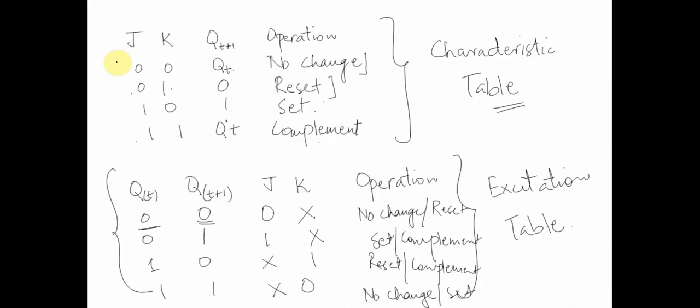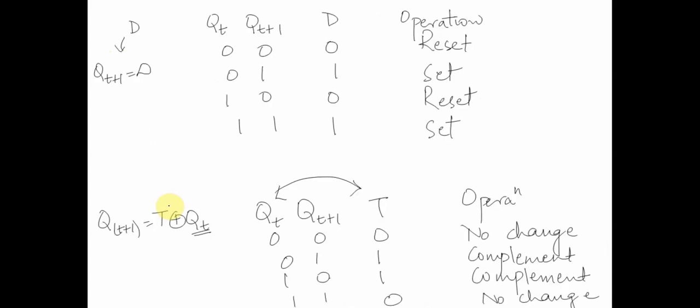One thing I want to quickly capture over here is that we spoke about excitation tables, right? We saw this is the excitation table of the JK flip-flop, and this is the excitation table of D and T. Once we notice, if given a scenario where we have to implement a circuit, it's easiest to do it using a D flip-flop, because in a D flip-flop our next state is equal to present state D, correct?